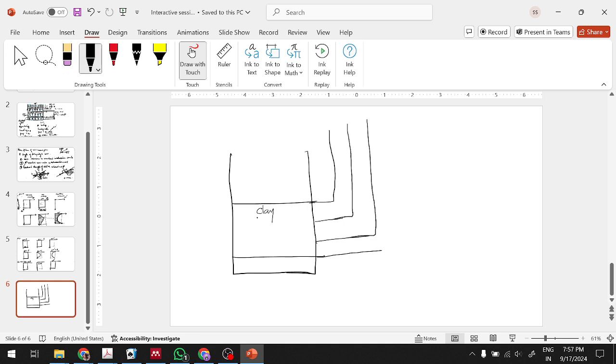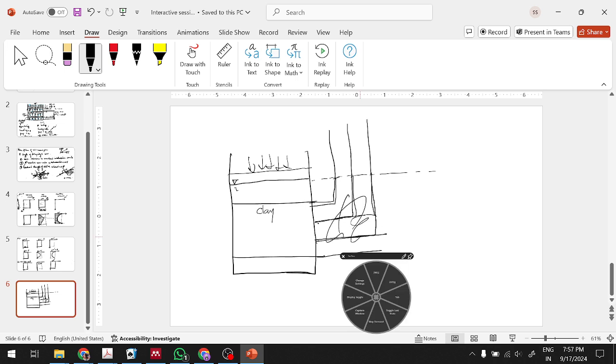If we attach these piezometers, let's say that your water level initially was here, okay, and you applied a load at time t equals to 0. So before applying the load, all the piezometers would read up to here. This would be, remember, in a no flow condition. If the water was flowing, then the piezometers would have some other readings.